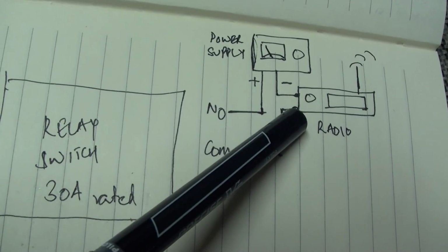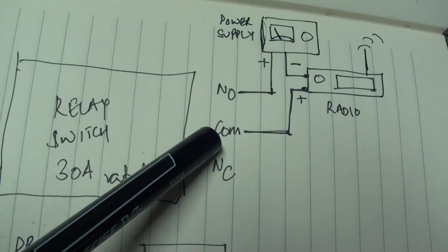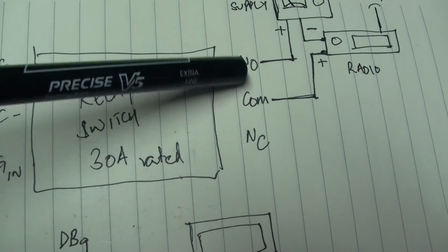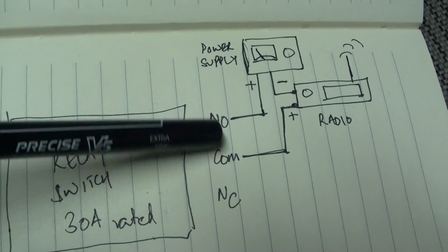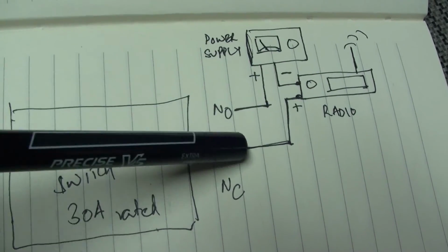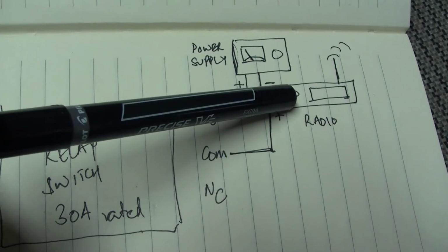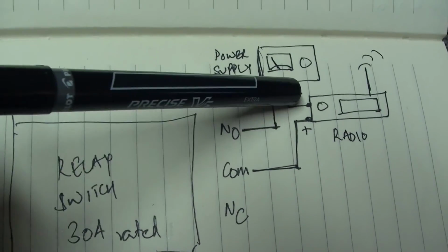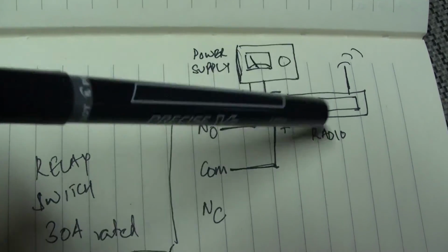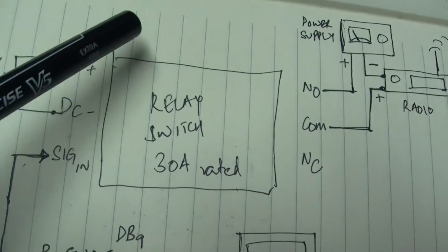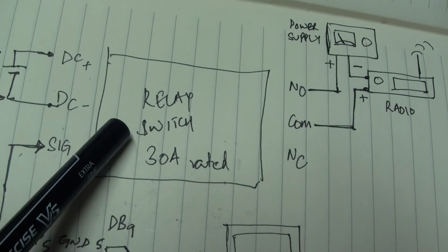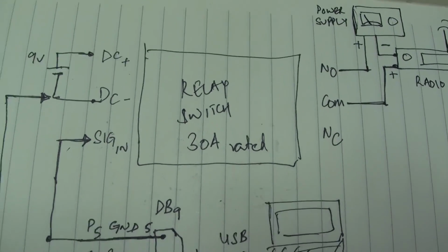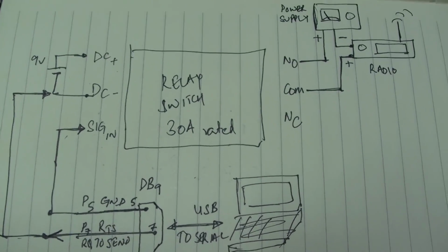and the other positive side of the radio is hooked up to the common, so that when the relay engages, these two wires are shorted or connected so that this circuit completes and the radio is powered up. When the relay disengages, the circuit is open so that the radio switches itself off. And this happens automatically every time the pass-through occurs in the STPO tool we just talked about. So let's go to a quick short demo and I'll be right back.